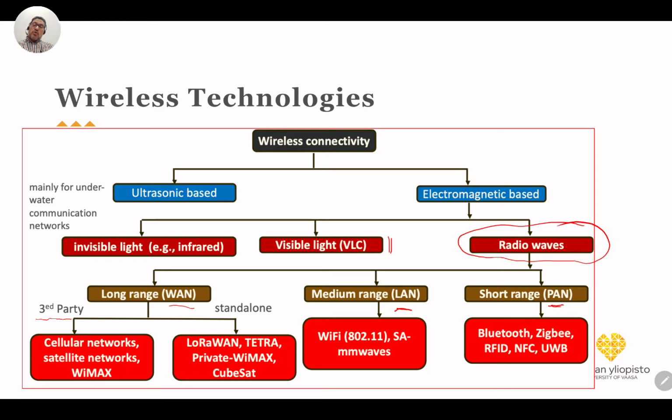There are also some other issues related to the quality of service, as we mentioned before, like delay in delivering packets, especially in automation applications, for example in protection or taking some control signal that you want to use to control some part of your grid or your system. In that case, the delay can be a problem. Cellular networks were not able to deliver messages at very small latency, like less than 1 or 2 milliseconds. But now with 5G and also the coming 6G, this will be handled and resolved.